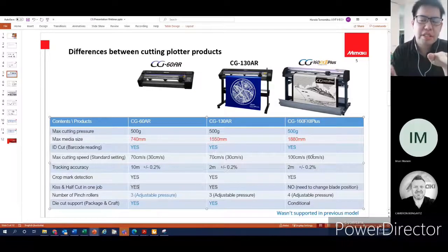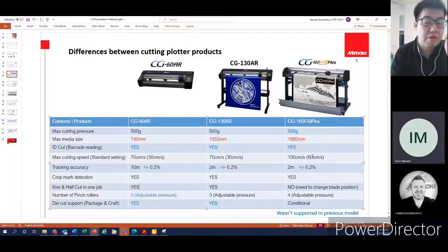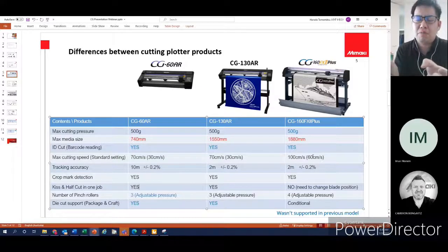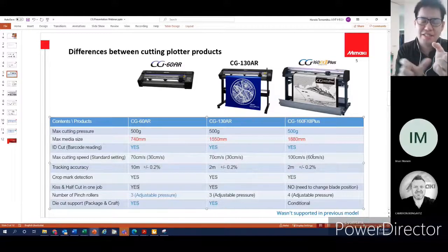So if you've got a different pressure on both sides of the media, it skews easily. So in that case, after you detect the media, you need to tell the machine how many pinch rollers are on the media, like 3 or 4 or maybe 2. Yep. That way, when the machine goes to change from print to cut, it will change the pinch roller pressure automatically, because CJV3s change the pinch roller pressure automatically with a lever by machine side, by having information from software.